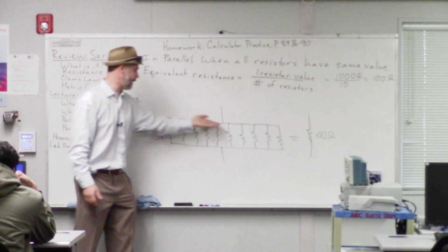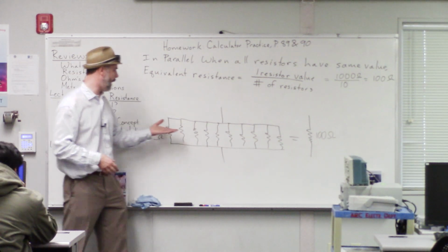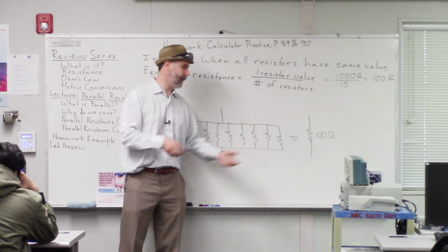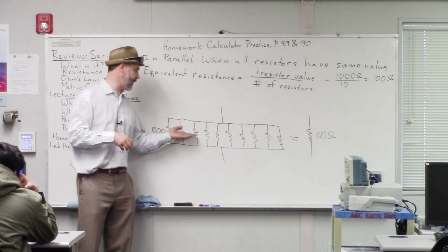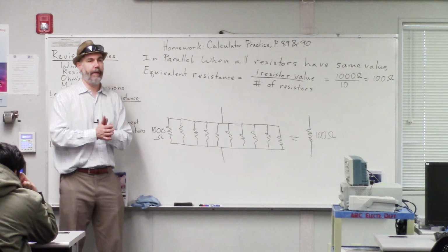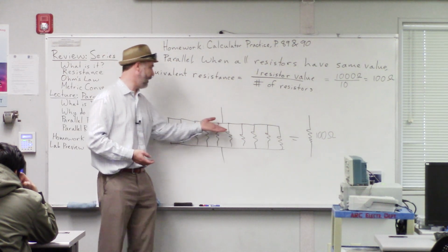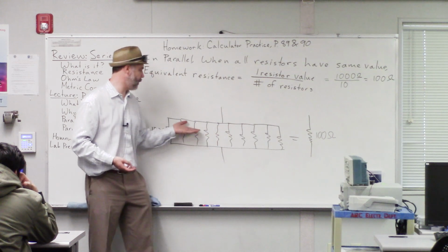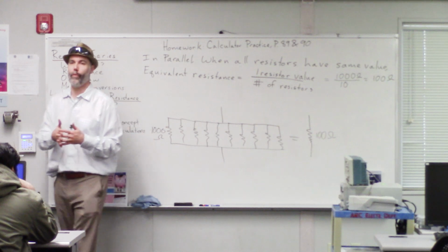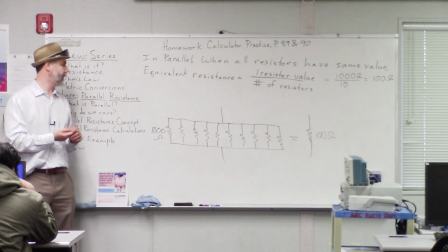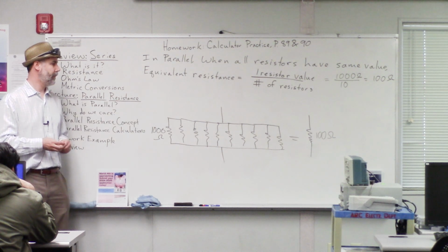So this is the type of circuit that person built. They had like a paint can that had a whole bunch of resistors inside, and then it was filled up with oil. So when those resistors heated up, the oil dissipated that heat, and they didn't get too hot. And also you had 10 or 20 resistors all in parallel, spreading that load and that heat around so that no one component got too hot. Okay? So that's another example of where parallel circuits worked.